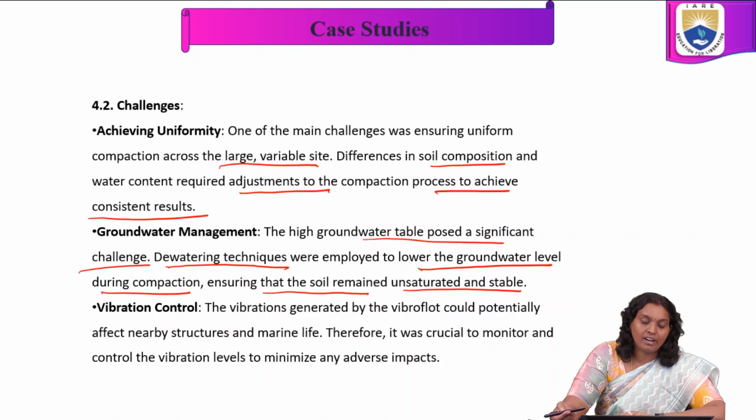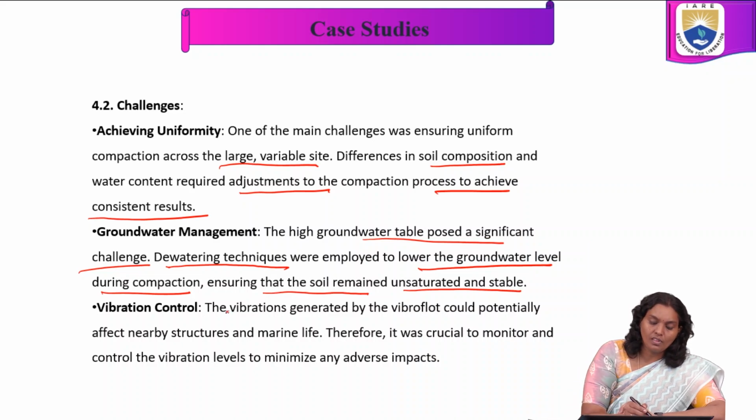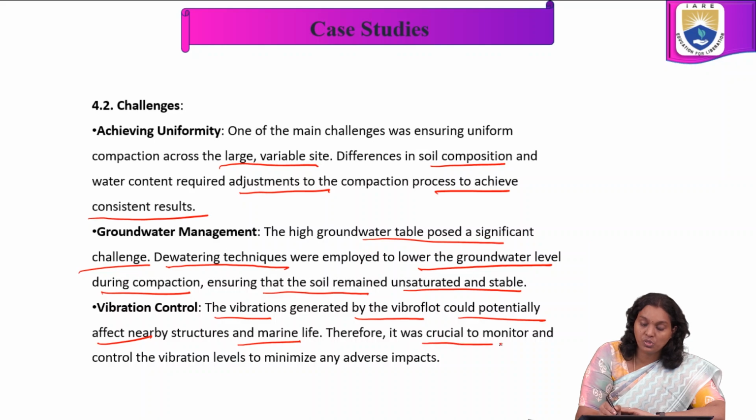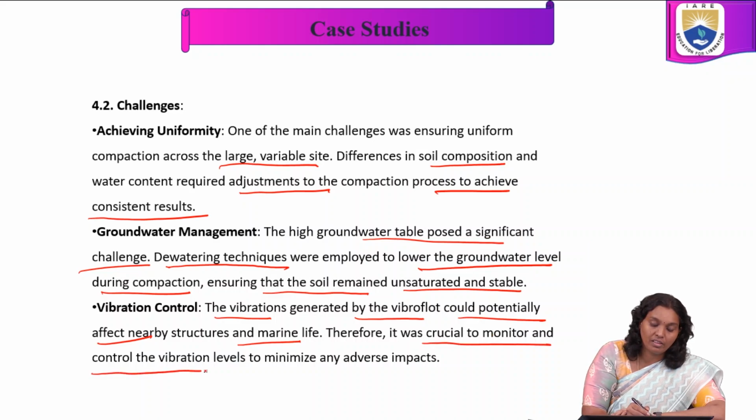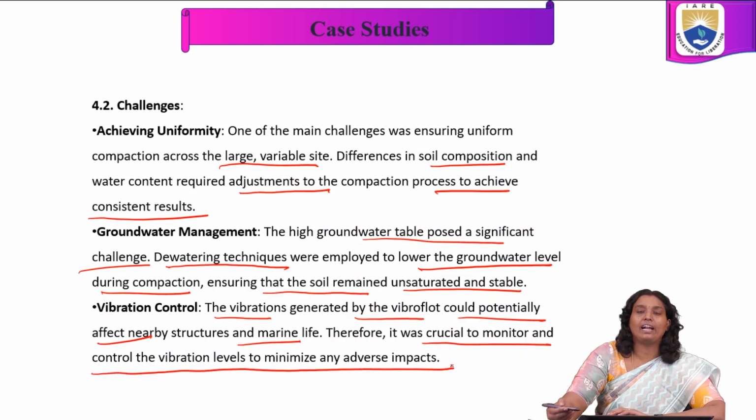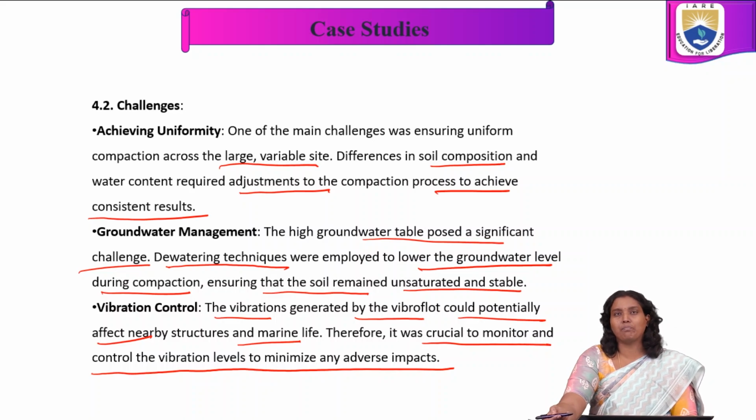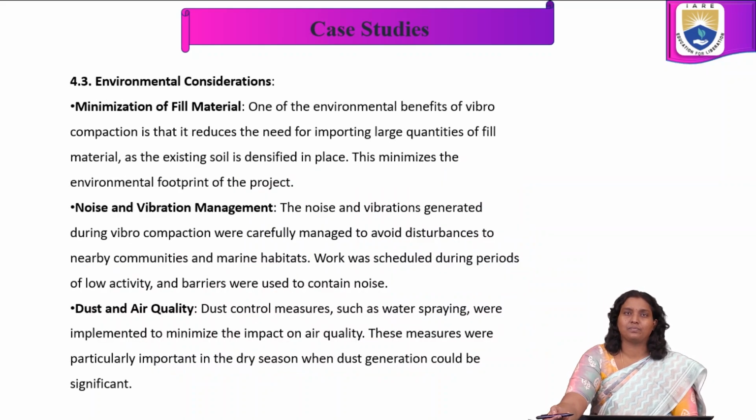As a part of vibration control, the vibration generated by the vibroflot could potentially affect nearby structures and marine life. Therefore, it was crucial to monitor and control the vibration levels to minimize any adverse impacts. These are the challenges. As a part of environmental considerations: minimization of fill material, noise and vibration management, dust and air quality control.